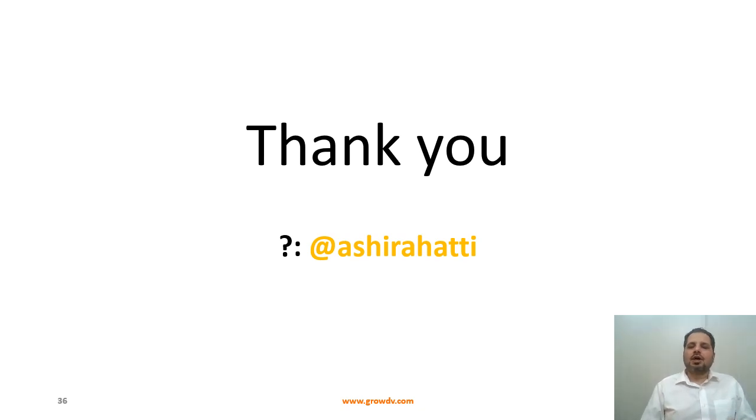Additionally, we saw how the procedural-based randomization can be strengthened with the weighted randcase statement, which is very useful especially if you are trying to do a percentage-based error injection type of application. The randcase is very useful for procedural randomization. And we also saw this advanced construct called randsequence, where you can define a grammar. That grammar you have to think of like a BNF format or a tree-type format, and you can define the order of the sequence that you want to generate, and within each of those productions, how you want it to randomly follow the path hierarchically. That can be defined within the randsequence, and it can be utilized.